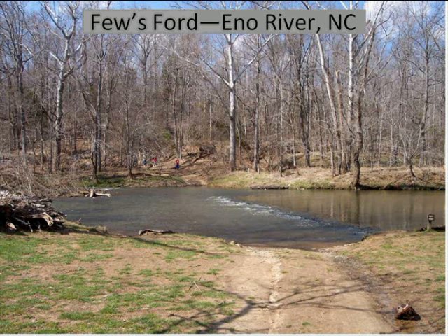So, with some of those larger landscape factors in mind and maybe a few of those field guides in hand, let's move into a general discussion about low water crossings and then talk more about types and designs with reference to watershed location. Low water crossings or fords are often associated with historic sites and trails used by native peoples and early explorers. Generally, they're found at sites created by hydraulic controls like riffles or bedrock outcroppings that offer a uniform, relatively shallow spot that remains stable over time.